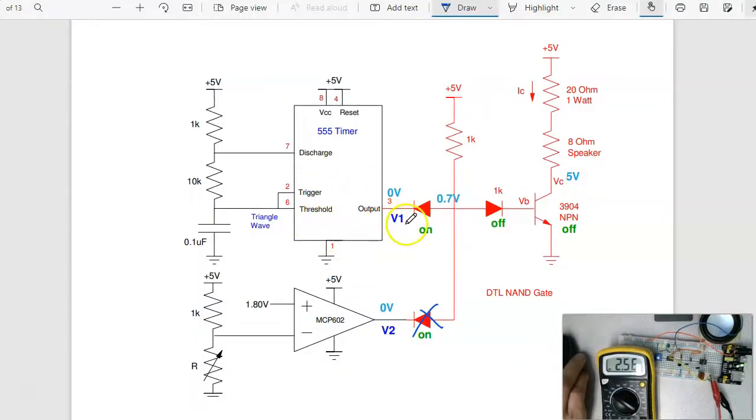So that was just building in hardware. Should match what you calculated. This voltage right here is how I control where it turns on and off. That's basically my thermostat. Whatever voltage corresponds to the temperature that I care about, switch at that voltage. When it gets hotter, this voltage drops, and the alarm goes on. When it gets colder, R goes up, voltage goes up, it turns off.